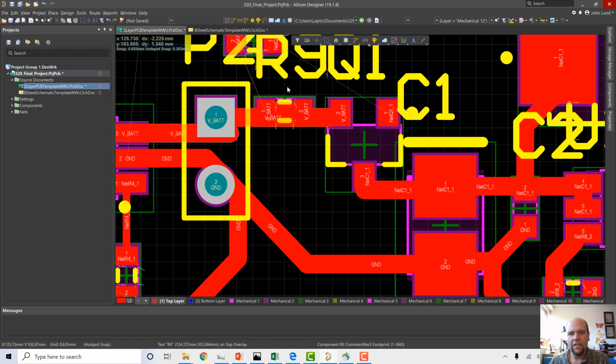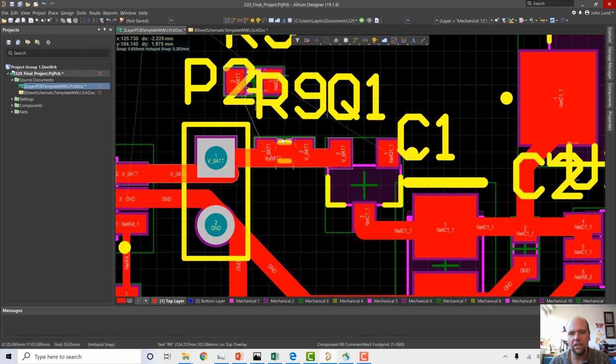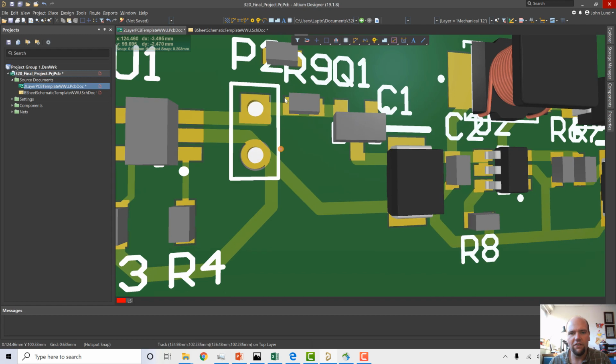These are kind of like a cut trace. A cut trace is a part that's specifically meant to be cut to give you the option to cut it. The main difference being a cut trace is actually going to expose the metal here. Although if you're cutting copper with a razor blade, it's going to go right through the solder mask anyway. So it's just a little tool for prototyping for us to do this trick. And it doesn't really change much. Mostly it just gives us these copper pads underneath here.